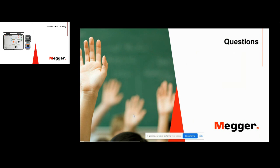Okay, that's going to depend on whether it's a grounded system or an ungrounded system. If you have a grounded system that has a low path to earth, this is not the type of system to use for that. If you're having an ungrounded system, that's possible. Now, this could also be used on an IT grounded AC system. To do that, you would need a special filter, which is optional. But let me first describe what I mean by an IT grounded AC system.